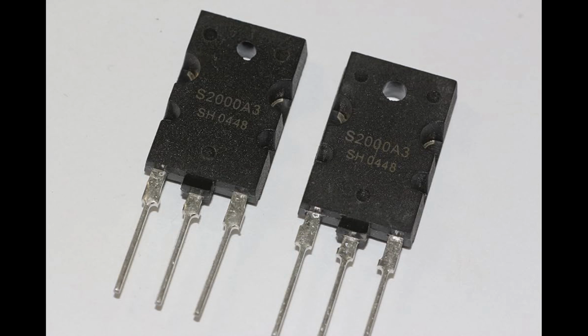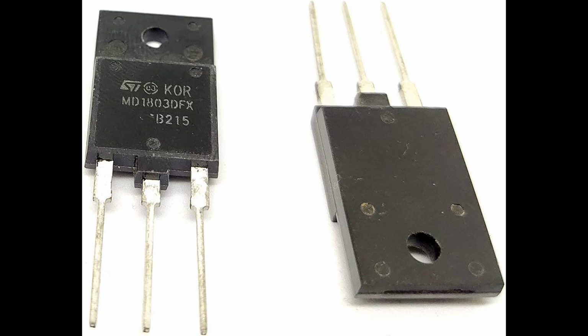Crystal oscillator: although crystal oscillators primarily use piezoelectric quartz crystals, they often include transistor amplifiers to boost the crystal's signal to the required amplitude. Crystal oscillators are extremely stable and are used as precise clock sources in digital circuits. Applications of oscillators with transistors include clock generators. Oscillators with transistors are essential for generating clock signals in digital systems like microprocessors, microcontrollers, and FPGAs.